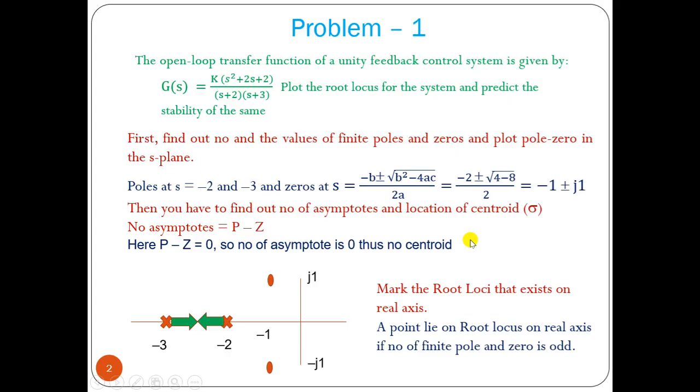I have uploaded the concept of root locus, the locus or movement of poles in the S plane as we vary the k value from 0 to infinity. From that we can predict the nature of the system, that is the stability and the output response.